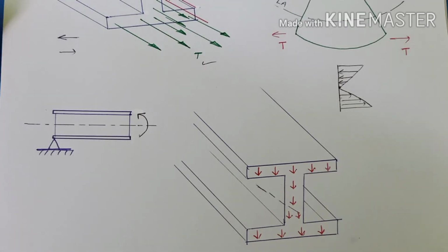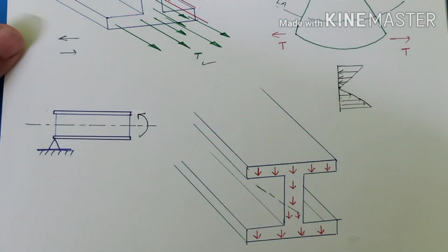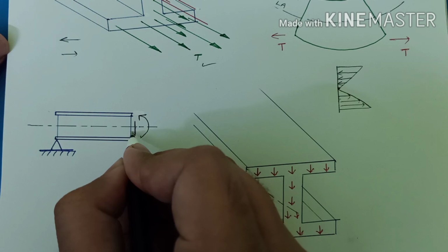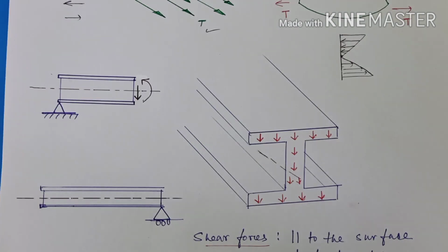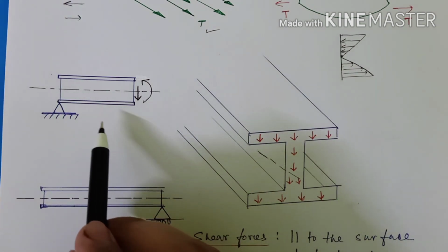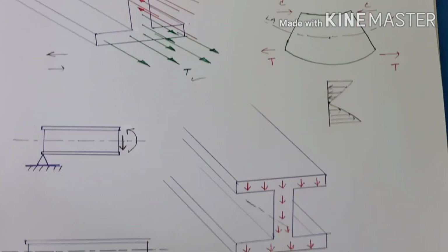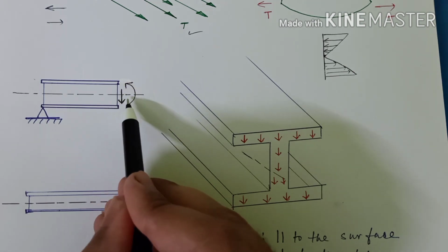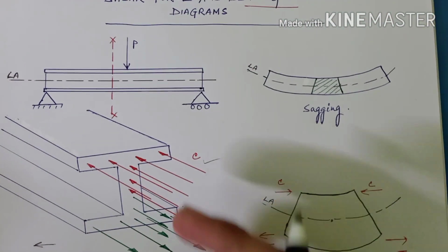So basically, if you section this beam, we are getting two phenomena. The first one is moment, and the second one is shear force. The shear forces are acting in the downward direction, right? So we can represent this like this, right? One thing to note over here, if we are concentrating on this diagram, that is if we are cutting the section from the left, we are getting something like this. That is a shear force acting downwards and a bending moment which is anti-clockwise, right?